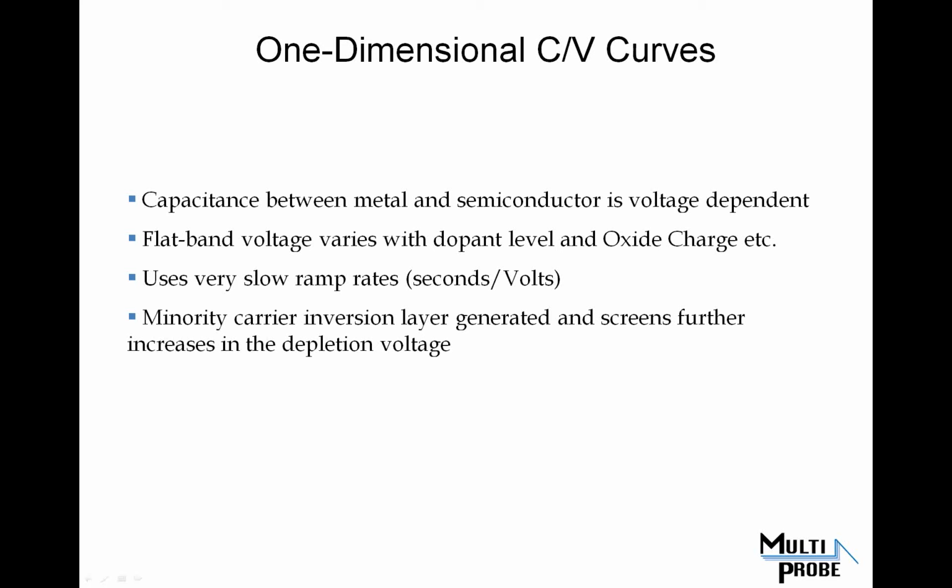So I was talking about CV curves and moving the charge around underneath them. I was going to say that the capacitance sensor that we use to do imaging with is creating a tiny little device that is a few nanometers on the side, and that's how it creates the image. The capacitance changes there are less than attofarads that you are able to measure in order to create an image.